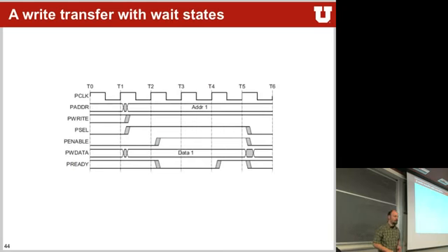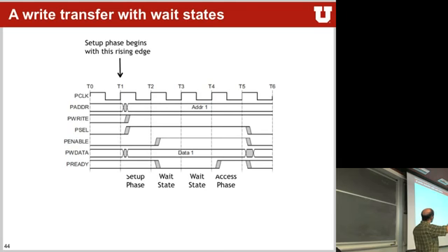You do have a wait state still. So APB can wait and can tell you to wait. In this particular case, it's the ready line. We have the setup phase over here where everything gets set up. We set up the address on this clock edge, whether it's a read or a write, and which peripheral gets selected. On the next one, we get the enable phase where this line gets pulled up, which basically means you can now go and access your data. We have the data down here. We can pull the line down, telling it that, hey, wait, this data hasn't been picked up yet, until the line gets pulled up. Then in the next phase, the access phase is done and the data disappears. The bus gets let go and the next transfer can happen over here.